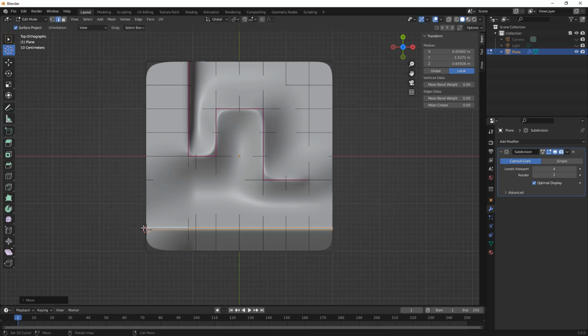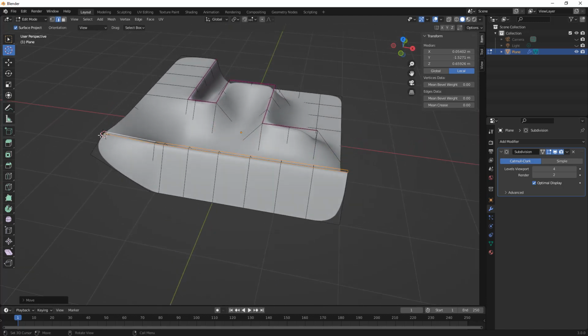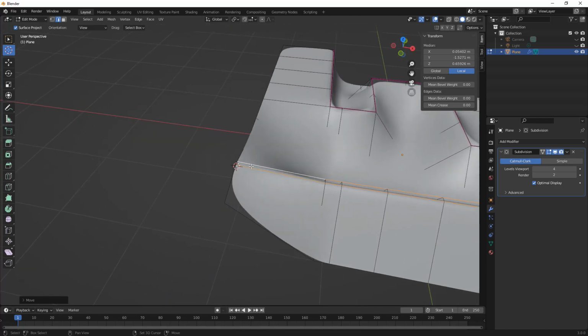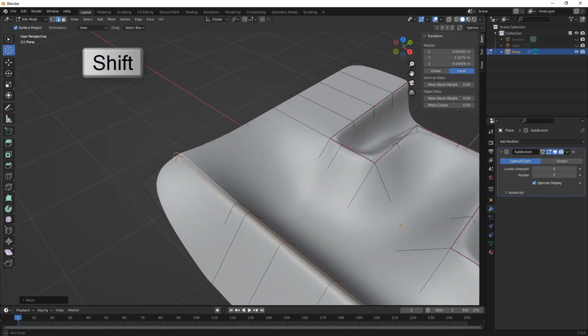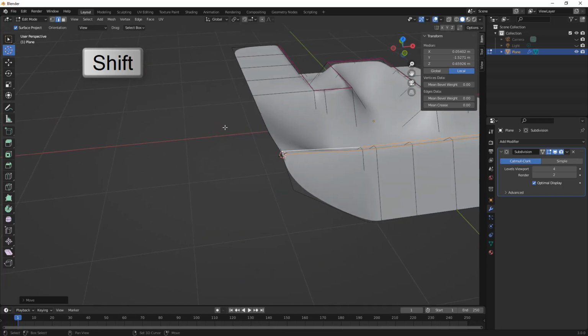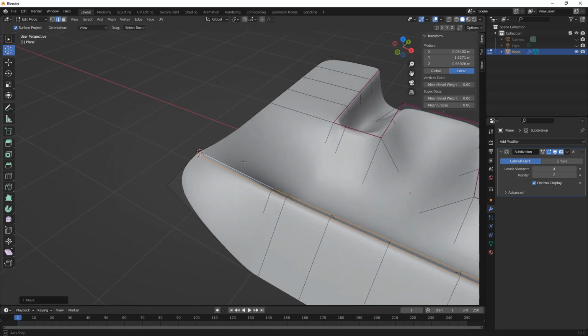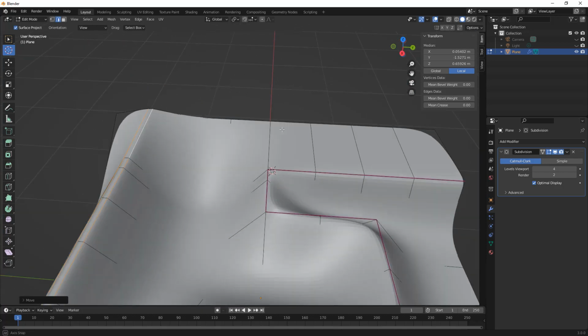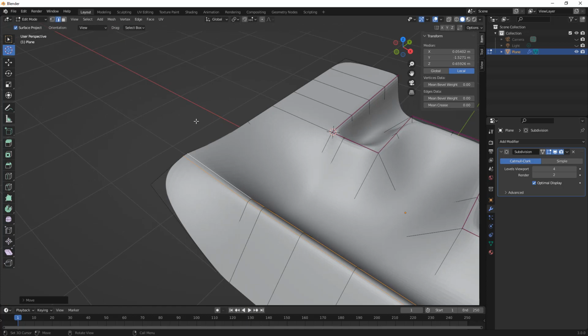So this can be helpful for us to sort of drag it into a general location, but if we're trying to be real specific and snap it to something, then obviously it doesn't help. We can also use Shift and right click, and Shift and right click allows us to place the cursor wherever our mouse is going to be. So you can see that this makes it a little bit easier for us to place it at a very specific location. So holding down Shift and right clicking the mouse, I can place it about where I want it. It's still not snapping to anything though.